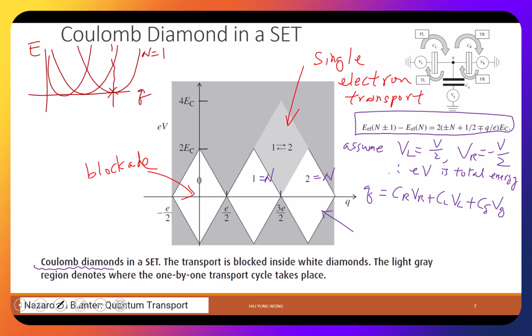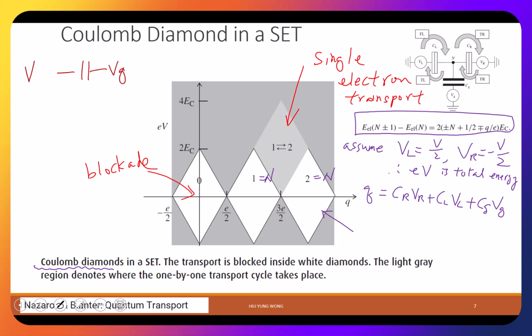It means at this gate voltage, you will have 1 electron in the quantum dot, because 0 electrons will give you a higher energy compared to the other electron numbers. That was for another problem, where we had a gate coupled to the quantum dot, and then a reservoir, just a two-terminal device from last time. So you can take a look.